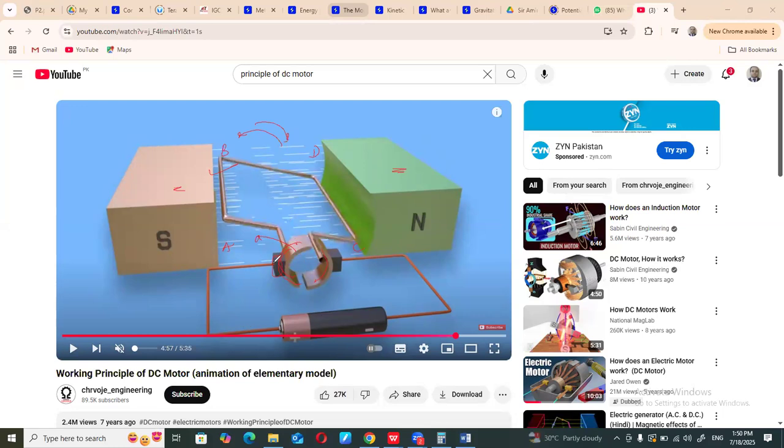So if somebody asks you what the job of carbon brushes is, carbon brushes just provide a proper, secure and safe connection between the armature assembly and the power supply. Then you have that device, and I already told you that it makes sure that the armature core will be rotating in one direction by simply switching the current when it is required. Okay, so this is the function of a motor.